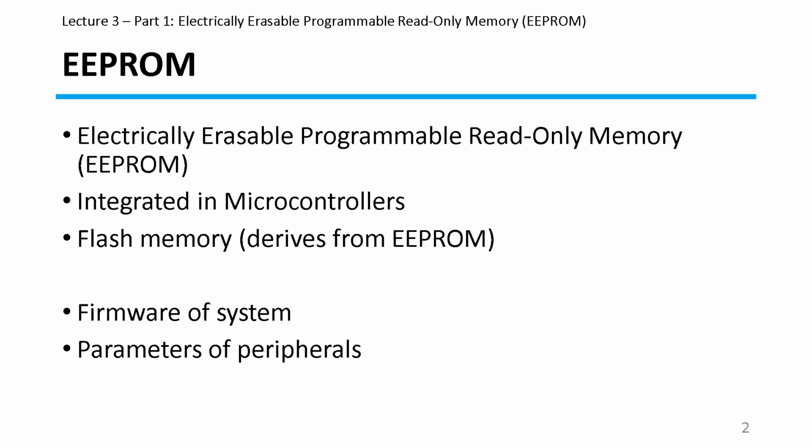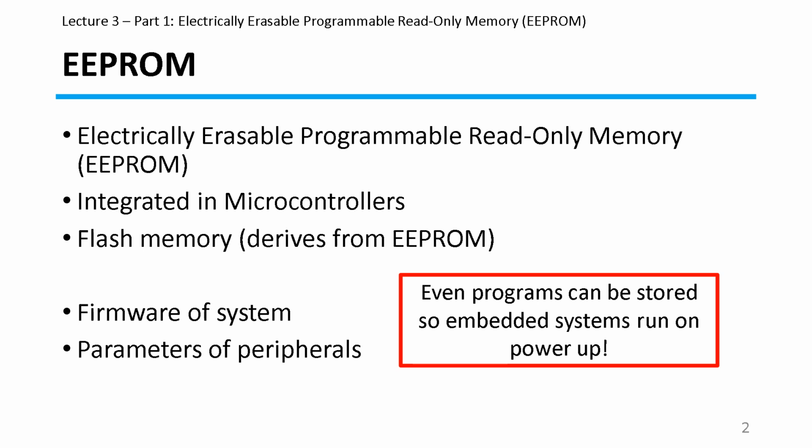Now, something to note here is that EEPROM can even store whole programs. In that way, the EEPROM gets loaded straight away when you power it up, and thus you don't need your microcontroller to be connected to your device.